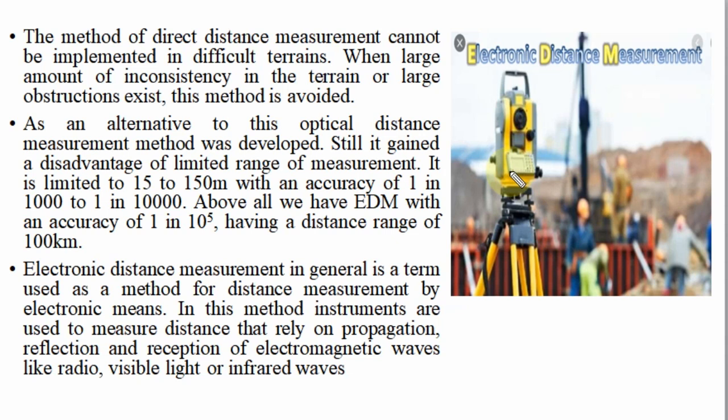Still, it has some advantages. It is limited to 15 to 150 meters with an accuracy of 1 in 1000 to 1 in 10,000. Above all, we have EDM, an instrument with a larger accuracy.